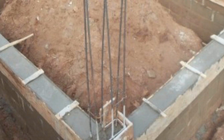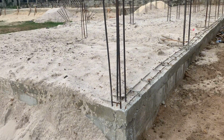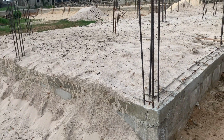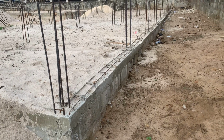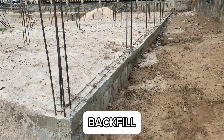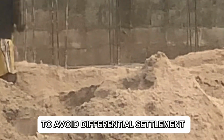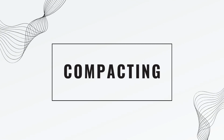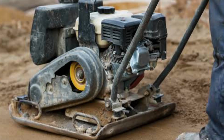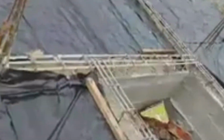Now, the next stage we are going to be talking about is the sand filling to the DPC. And remember, the DPC is a damp-proof course. Okay. Now, it is advisable to fill your foundation. You also backfill it. Okay, and also you water your foundation for differential settlement. Then after doing that, you go ahead to do what is called compacting like so. A damp-proof membrane is placed to prevent water from rising through.